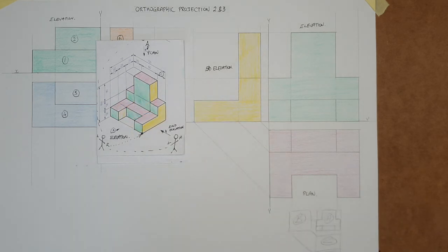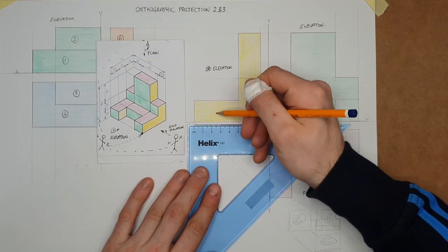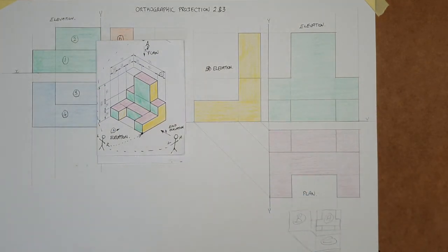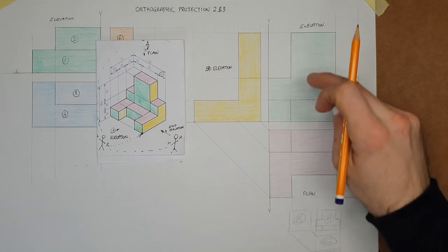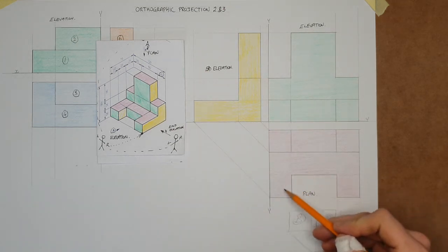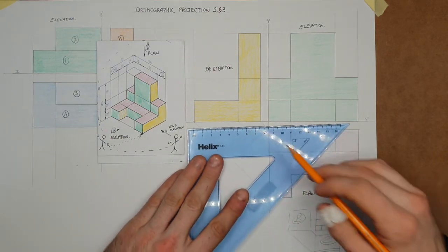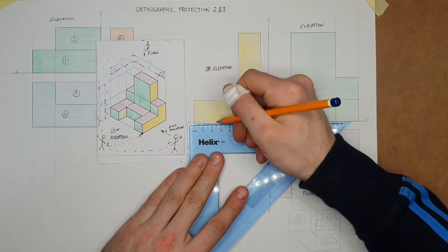We want to represent where this yellow surface goes in by 25. So what we might be tempted to do at this point is measure our 25 and draw a line, but don't forget what my rule was, there's no measuring in the end elevation because we've all of our dimensions coming from our views. So if we have all the dimensions we need, we don't need to measure anything over here. We need to bring it from the plan. I just said that what you'd be tempted to do is measure in 25.